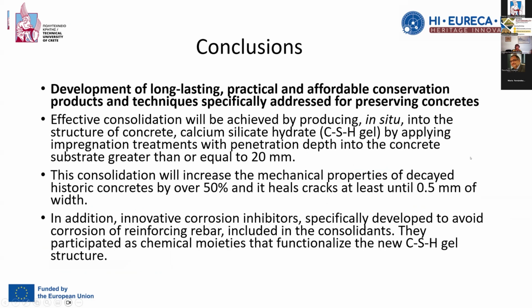And this effective consolidation was achieved by producing in situ those products and the calcium silicate hydrate gels by applying them on the surface of concrete with a penetration depth greater than or equal to 20 millimeters. This consolidation increased the mechanical properties of the decayed concrete by over 50% and healed the cracks until 0.5 millimeters